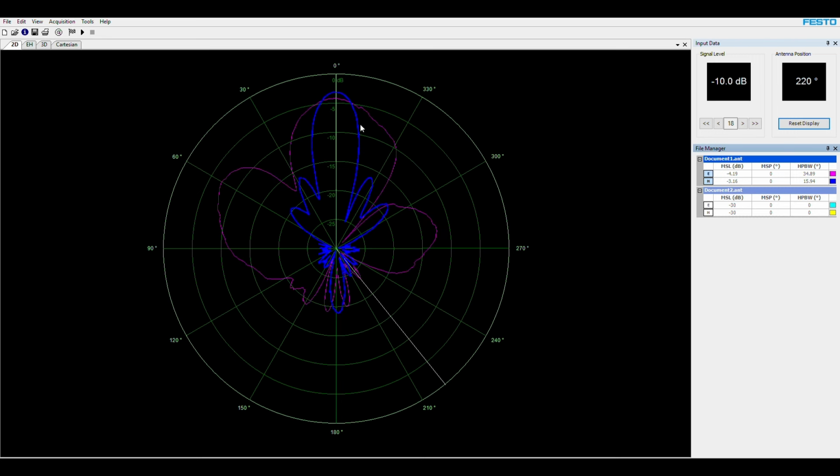Now, one thing that you know is that we should expect a similar signal at the maximum for these two antennas. So the H plane was minus 3.16. The E plane is minus 4.19 for the maximum signal level. If you look at the right column, you see minus 4.19 for E plane, minus 3.16 for H plane. So that 1 dB we accept to be okay for the sake of this experiment.